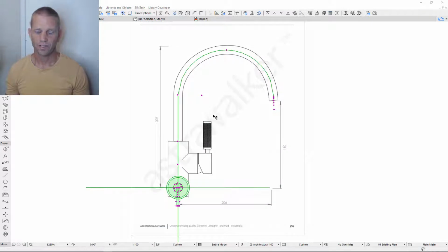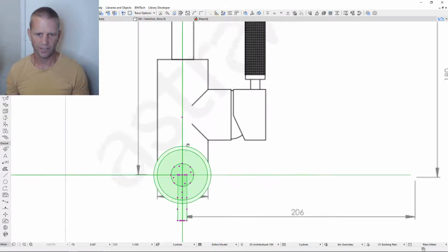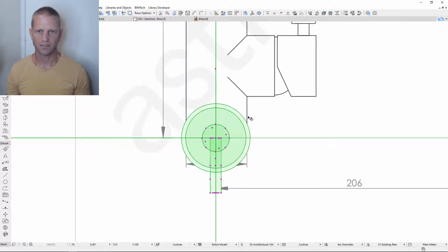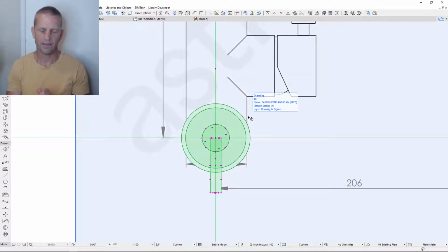Okay, now that we've defined the spout, we need to go in and do this tap. We need to access the geometry of this tap as well, and to do so we actually need to go into those elements and adjust their positioning so we can get access to that. So you can see the element here, but you don't have access to all the guides because this element's made out of different shapes that are then rotated on different angles, and when you rotate the shape on a different angle, the guides disappear, so you need to set those angles back to 0 to access the guides.